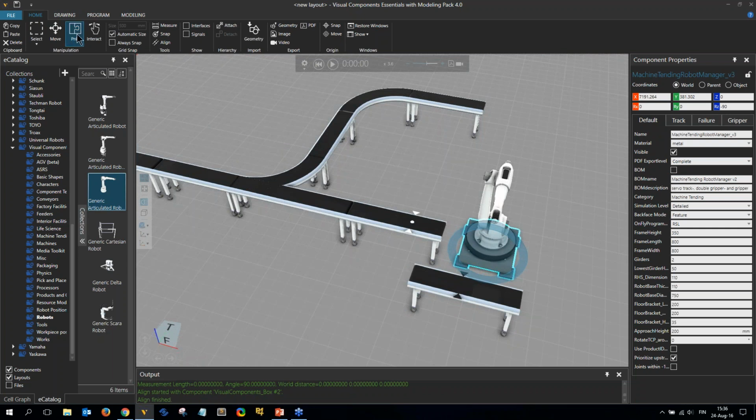We do connections with plug and play and dragging components together, but you can also do remote connections, which are called abstract connections in Visual Components, by enabling interfaces here. Then when you select a component that has interfaces, this little label is shown. And there's a connect process stages interface. I can start dragging a line from that connection. I can drop it there.